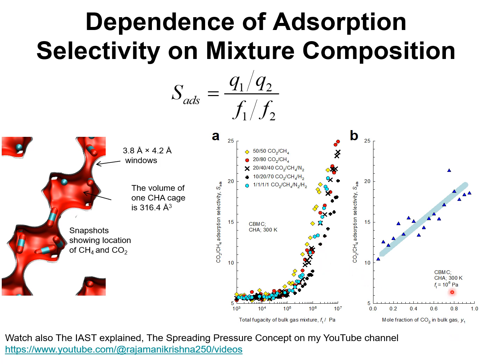To highlight that aspect, I take a binary mixture at a total pressure of 10 to the power 6 Pascal, or 1 megapascal, and I plot the adsorption selectivity as a function of the mole fraction of CO2 in the bulk gas phase. We note that the CO2/methane selectivity increases by a factor of 2, from 10 to about 20, as the mole fraction of CO2 in the bulk gas mixture increases.